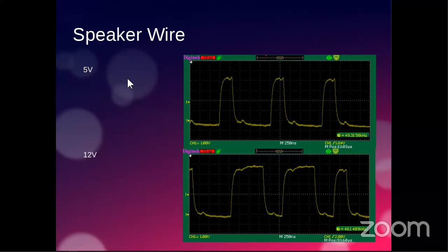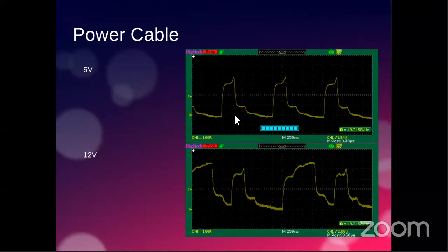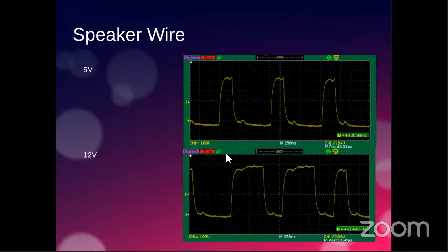It's possible because whereas the wires are all bundled tightly together with the speaker wire, the third wire was sort of just loosely cable tied to the other dual core wire. And so it's possible that the capacitance between the wires was different and that changed the way the signal shape was. But this one here actually turned out to be pretty good.